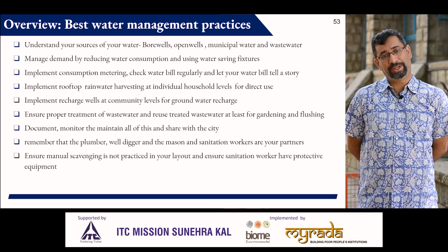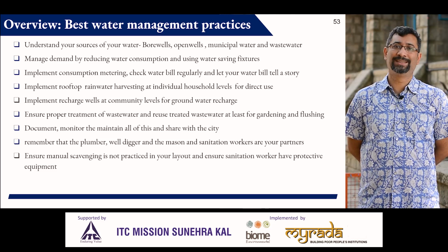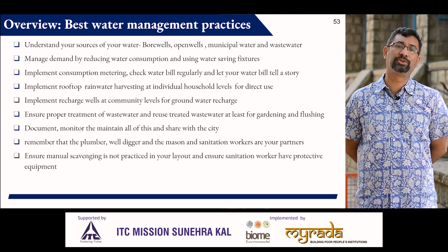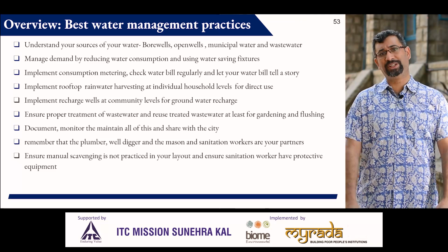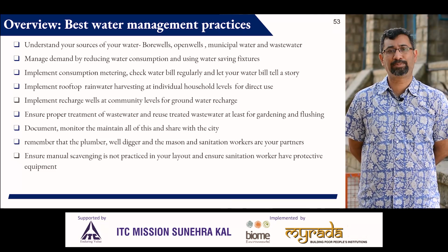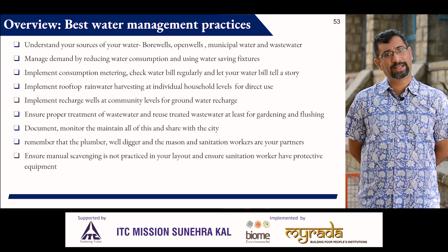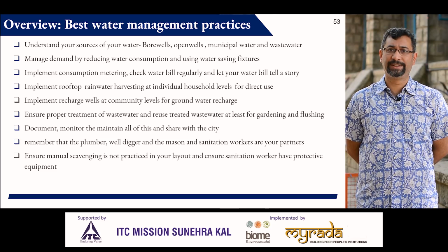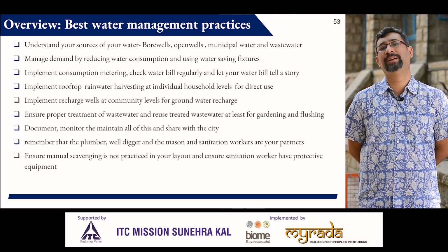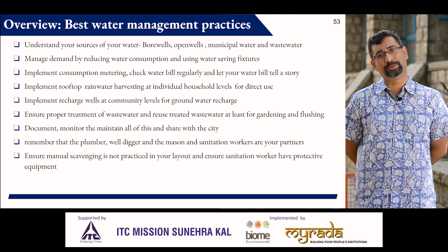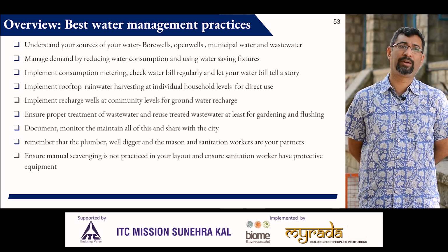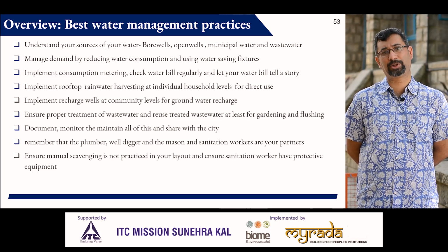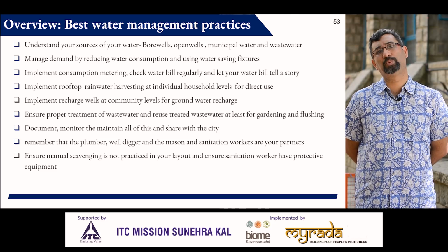As you work on managing your demand, you can actually start looking at each household within the community as a place to harvest rainwater. Rooftops are usually clean surfaces, so you can capture rooftop water, store it in tanks, and the household can actually use it. And this much water the household now does not need to depend on the community's water supply. Similarly, water that's falling on clean roads or water that cannot be stored in storages from rooftops can all be led to recharge wells.